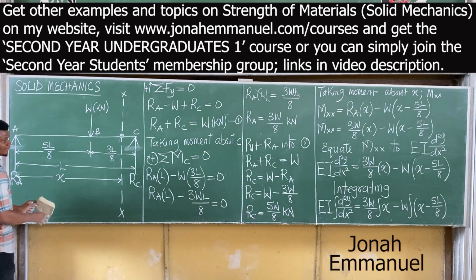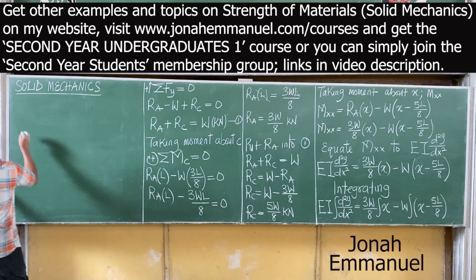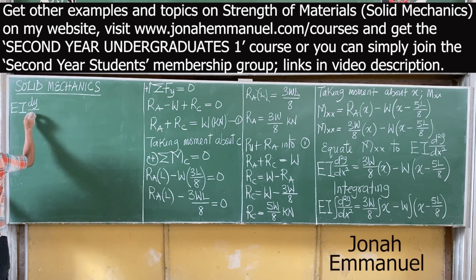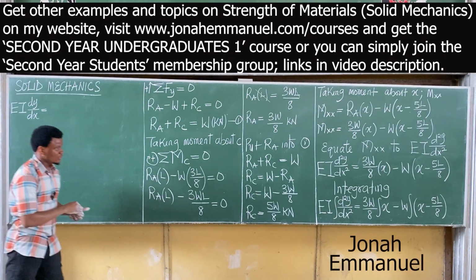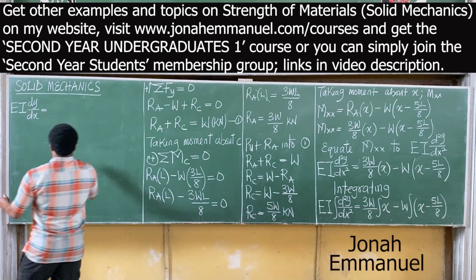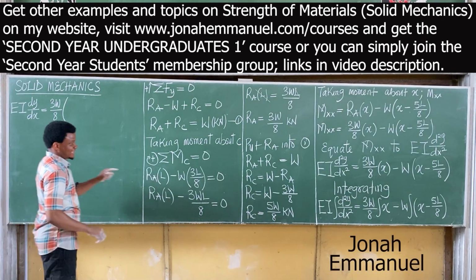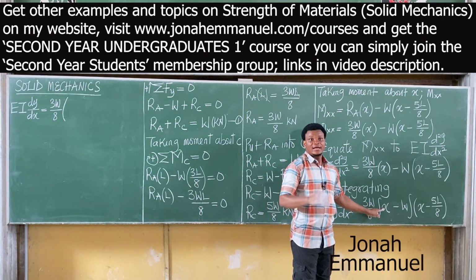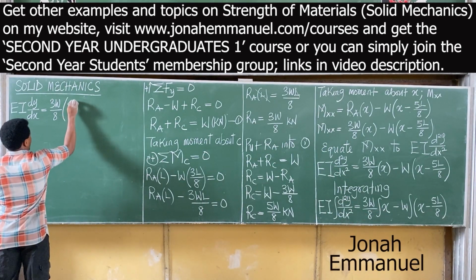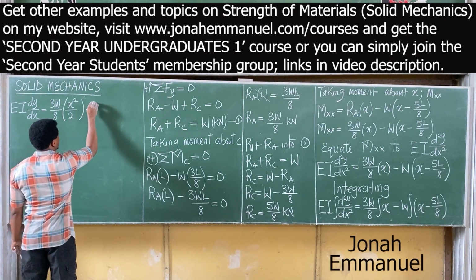So what do you have here? EI dy/dx is equal to, what do you have here? 3W over 8, integrate x here. What do you get there? x squared over 2. So it becomes x squared over 2 minus W.